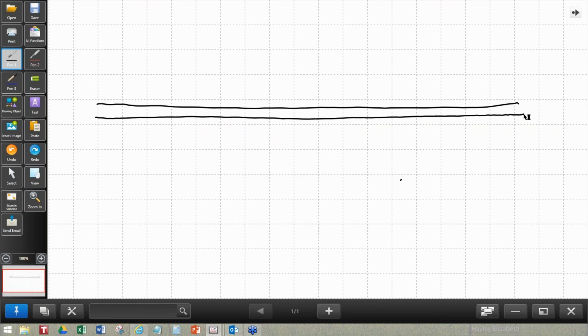Because you can put added charge into each segment and change its electric field. I can take some Q and put it onto here. I can change its voltage, and I can generate an electric field off into space. That electric field stores energy. Hence, this thing has the ability to exhibit the equivalent of capacitance per unit length.